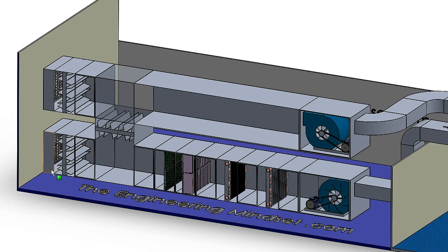It's coming in through the grills, then past the dampers. It's got the panel filters here, then the bag filters, then it's passing through these coils. In this configuration I've done it that heating is first and then cooling. You may have it just heating, you may have it just cooling, you may have cooling before, and you might have some humidifiers, etc. in there. But this is fairly typical, at least for the UK and most of Europe.